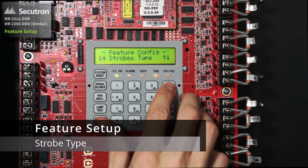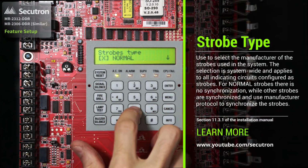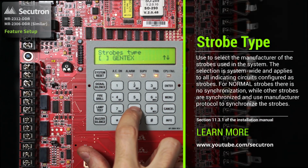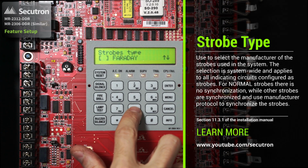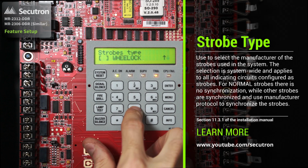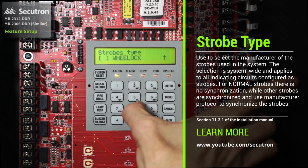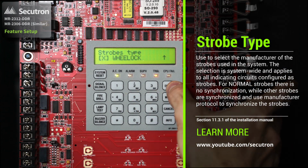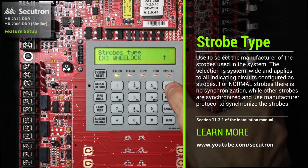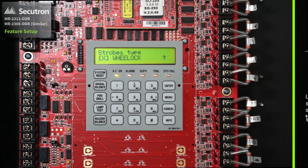Our next feature is our strobe type. So if we select the strobe type, by default it's been selected as normal, but we can have either the Gentex, System Sensor, Mircom, Faraday, or Wheelock selections. Once we've located the desired selection, we can hit the left or right cursor to apply the X and press enter. We'll use this menu to select the manufacturer of the strobes that we're using on the system.